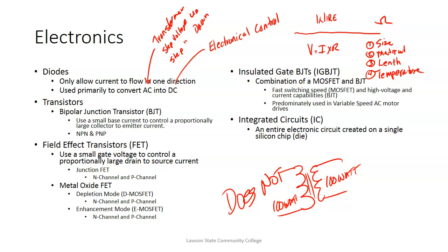You keep them real clean, because we only got about 12 volts to work with, and your starter wants 50 amps to turn that big engine over. 50 amps, 1 ohm, it would drop 50 volts. Well, we only got 12 volts. So 1 ohm means your starter wouldn't turn over. So that's why we have to do that.